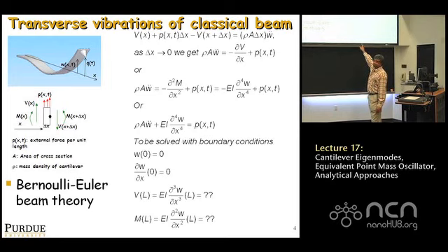So really what should happen is this shear force should equal mass times acceleration of the tip. That's what you should get. The force at the end of the beam should equal mass times acceleration of the tip. So if you set it equal to 0, you're effectively saying the mass of the tip is basically 0. And for the most part, that's not a bad assumption, because the mass of the tip is usually 10%, maybe 5% that of the mass of the cantilever. Maybe you can neglect it, but we'll discuss today that often you can't neglect it. Okay? So anyhow, I've left this with a question mark.